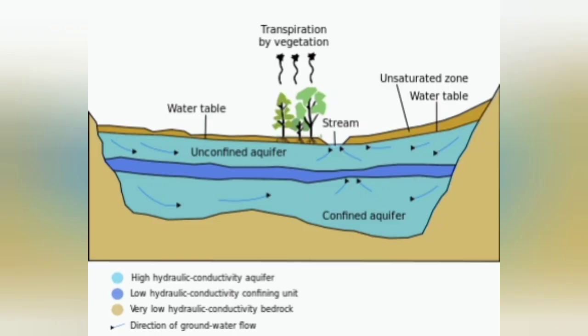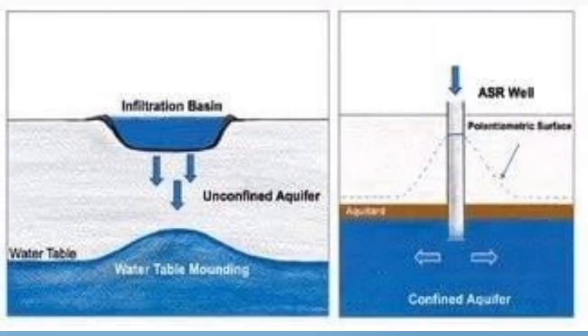Infiltration capacity depends on many factors such as the soil type, moisture content, organic matter, vegetative cover, season, air entrapment, formation of soil seals or crust, etc. Of the soil characteristics affecting infiltration, non-capillary porosity is perhaps the most important. Porosity determines the storage capacity and also affects the resistance to flow. Thus, infiltration tends to increase with porosity.